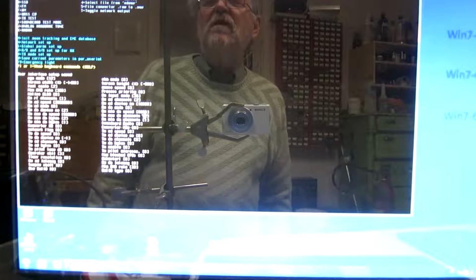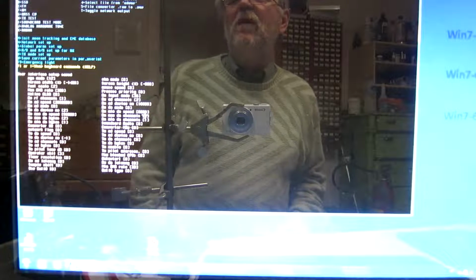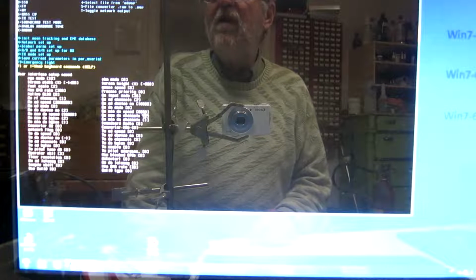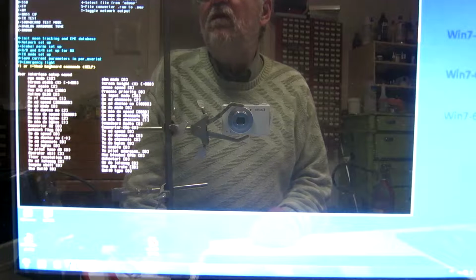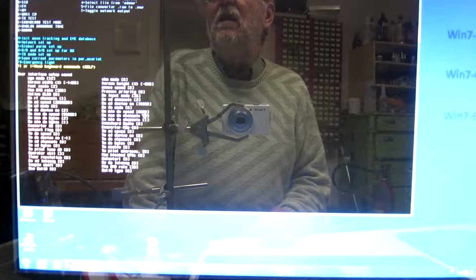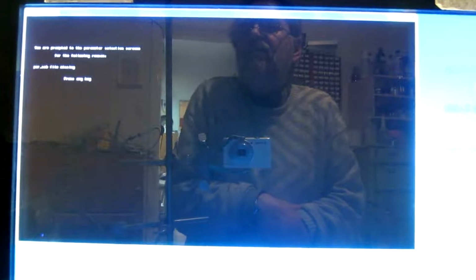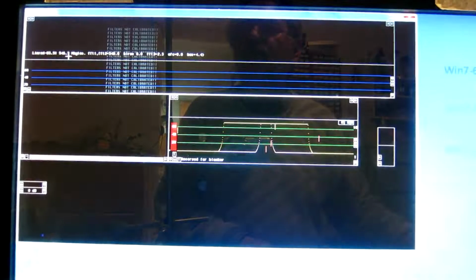What comes in those lists depends on what operating system I'm running, and I have too many and I cannot remember. Anyway, now it's saved. So let's go for calibration. I can make it in SSB mode, that's D. So I'm prompted to the parameter selection because there are no parameter files yet. And I enable the second FFT because I want to demonstrate the noise blanker a little bit later. But the other things I just accept the defaults.